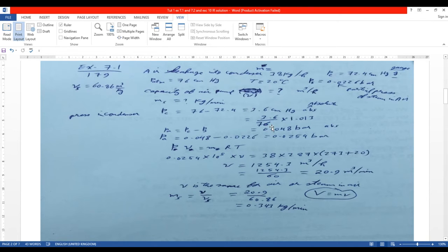We have to change it to meter in the equation rho g h. Then we get the value 1.01300 actually in Pascal. To change it to bar, we multiply by 10 to the minus 5. It becomes 1.013 bar. So that's how we find the relation between 76 centimeter mercury and 1.013 bar. So this is the atmospheric pressure.